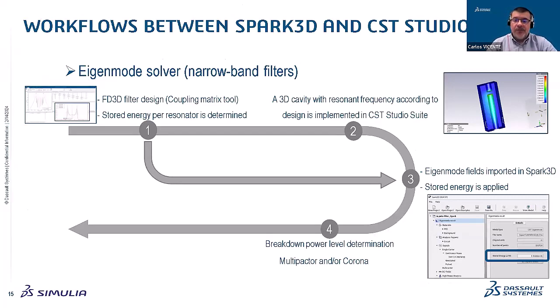Okay, and then of course the advantage is that if you don't meet the specifications, you can come back to step 2 and change your cavity. You can even go to step 1 and change the filter topology, because you may have a filter topology which results in lower stored energies. So you have the flexibility to do that before even thinking about the complete filter design, how the coupling will be, and so on and so forth. This really gives you a nice input before you go through the complete process.